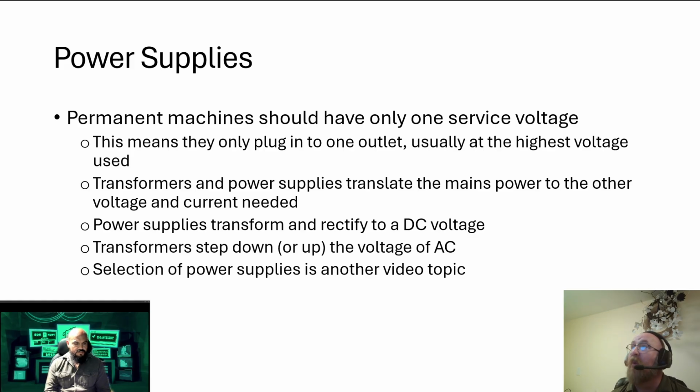There may be multiple power supplies meant to separate different ranges of current used by those things. So you'll see multiple power supplies in a lot of enclosures, in addition to one for different voltages. If you've got a lot of really high power, like really big hydraulic valves in your system, maybe there's a separate power supply for powering those solenoids than there is for powering your inputs.